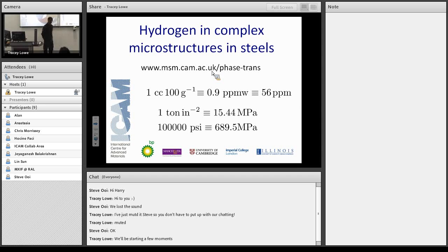So today I'm going to give this lecture for the first time. I haven't talked about this before, although we've been working on hydrogen in steels, the particular aspects that I'm going to talk about, for some time now. I thought I would begin by summarizing units, because remember, we are working in an international environment, and often you see units of hydrogen in steel quoted as centimeters cubed per gram, or parts per million by weight, or parts per million of atoms in the whole assembly of atoms. Similarly, we often talk about PSI, pounds per square inch. So this is the conversion unit between pounds per square inch and megapascals.